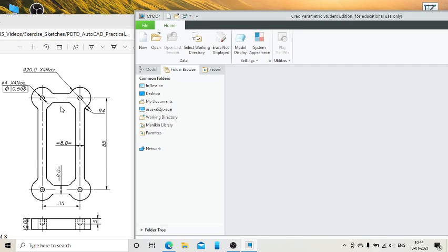So we have to design a simple jig using the given parameters. This is our component, some machined component. I think it is 10 mm thickness, so 5 mm depth, and we have to drill 4 holes of dia 4. So let us see how to design this particular template jig. Template jig in the sense, when we align the component, we should be able to locate it from some of the shapes which is available from the component, right?